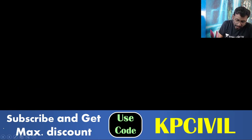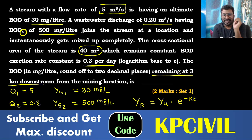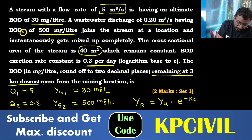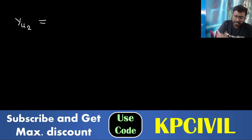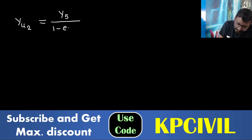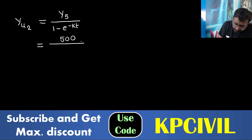But first we need the ultimate BOD for stream 2, because for stream 2, 5-day BOD is given, not ultimate BOD. That is the confusion in the question. Remember carefully, for stream 2 this is 5-day BOD, not ultimate BOD. So ultimate BOD for stream 2 is 5-day BOD by 1 minus e power minus kt. 5-day BOD, how much? 500. 500 divided by 1 minus e power minus 0.3 into 5.